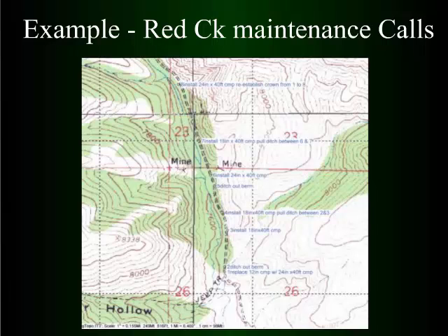I don't know if we've talked about that much yet, but the tendency on roads is to just blade them flat instead of putting a little bit of a crown in them. And a lot of times this is why you get a lot of the ponds and stuff in the roads here, is the water doesn't flow off of them. It doesn't take a whole lot of crown to move the water, but it's something that's important to establish and maintain in your roads.